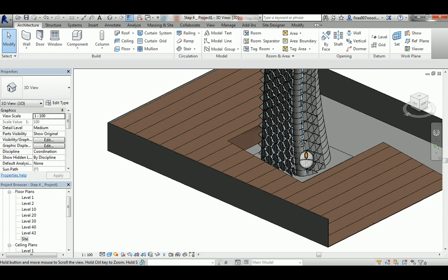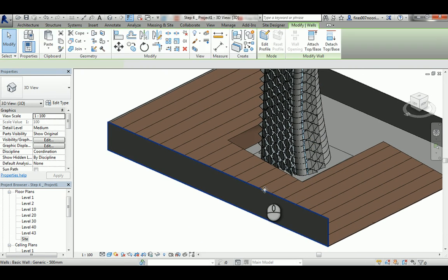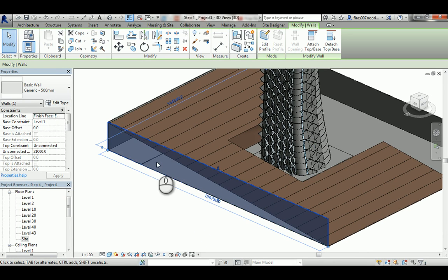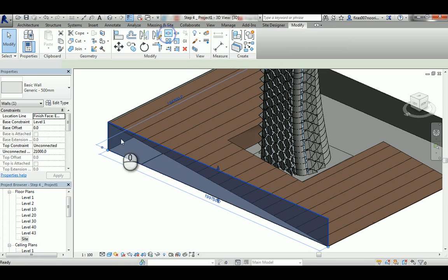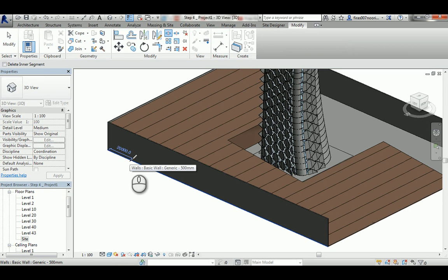So I'm not supposed to leave that like this, and I'm not really happy to make that inclined also, as it's really hard to be constructed, and easier if I just split that, and I'm gonna go like each 20 meters probably. So each 20 meters I'm cutting the wall.